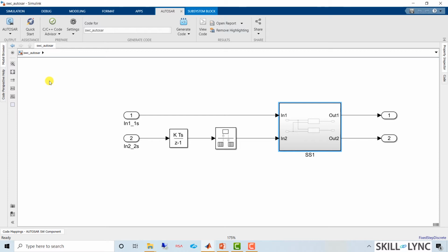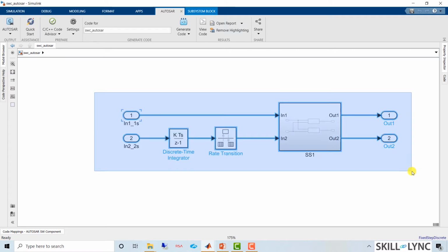The ultimate objective in this system is to make use of the NVRAM function, and then do code generation and see whether BSW software code is being generated appropriately. That's the whole idea here. First I am going to take this MATLAB model, which is already present in a subsystem within a model, into a separate model. Then in that separate model, what configuration parameters do we need to take care of?